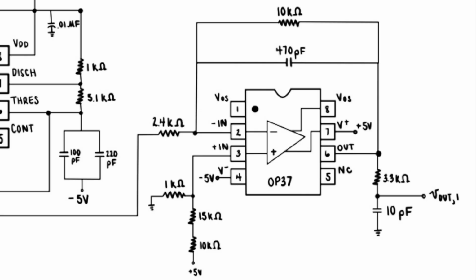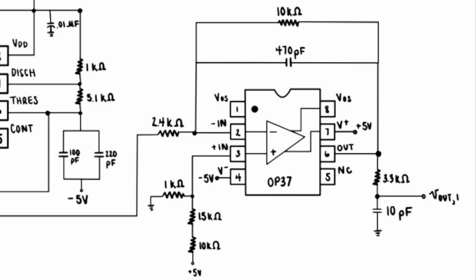When deciding which components to utilize for the integrator circuit, the equation RC equals Vin times period divided by 4 times the peak voltage desired was utilized, which is the equation for a simple op-amp integrator. The integrator calculations resulted in a resistor value of 5.2 kiloohms and a capacitor value of 470 picofarads.